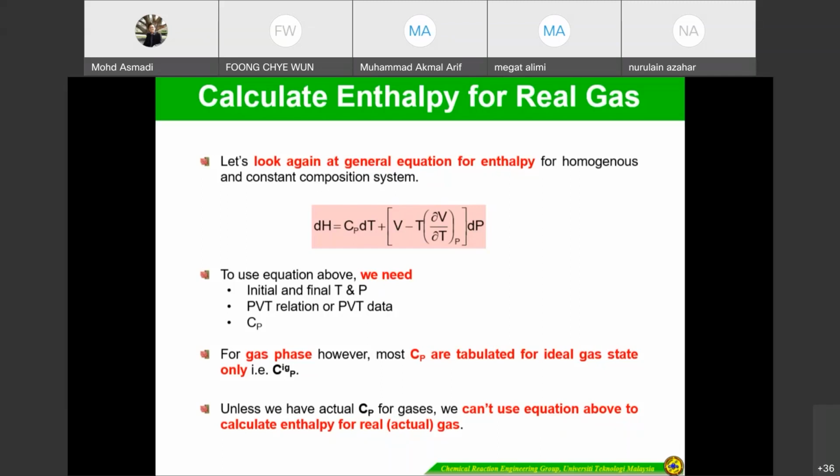You also have to consider the pressure and temperature, whether it's low to moderate or moderate to high. If just low to moderate, I would suggest just using the virial equation. That's all. No need to go to Lee-Kesler or cubic equation. And you have to consider whether it's polar or non-polar. Generally, what we deal with here is non-polar. If it is polar, you have to find an equation from another reference.